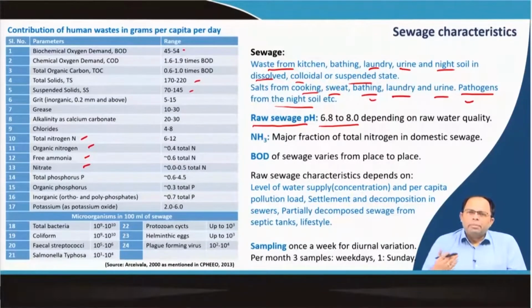While primary treatment reduces the total TSS, the total amount of solids, secondary treatment is primarily devised to remove the BOD from the waste. That means we also need to understand how much BOD we have to remove.